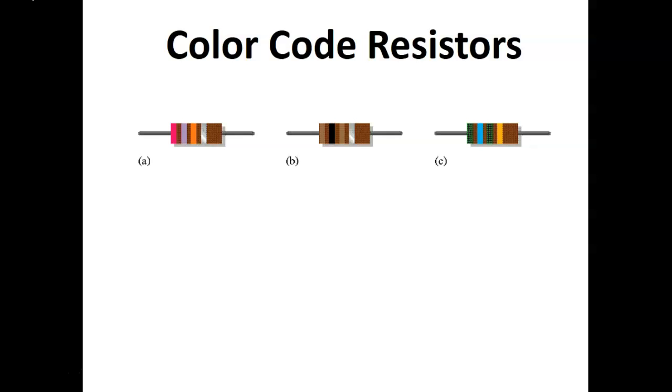So you're going to be saying 100 plus or minus 10. So your upper limit is 110. Your lower limit is 90. If your resistance, when you measure it, falls between 90 and 110, you have a good resistor. If it falls outside of those parameters, it is not a good resistor.